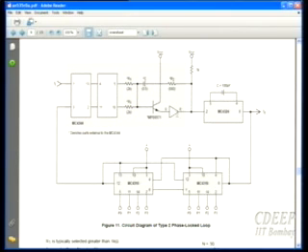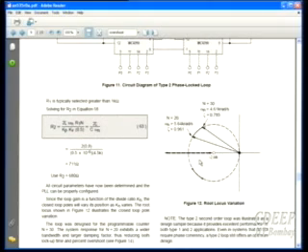This is that amplifier, this is on chip, okay, with the gain of A. This is that RC, series RC, this is off chip, with these two R values at the output of this phase detector. And this bipolar transistor is just the buffer, with the input of buffer and this resistor, output of this phase detector IC. And these are counters, and this is VCO. It's a very nice example, and then they have shown practical values they have achieved.